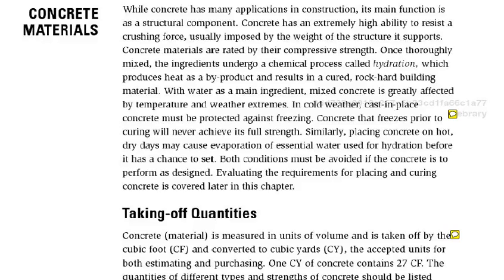And that's the second point. You want to do concrete work when the temperature is optimal. And so as you schedule work, you're going to consider when the concrete work is going to take place and how it times out on your schedule. And you may either be moving the whole schedule or you may be moving other activities to slide the concrete into a good temperature range.